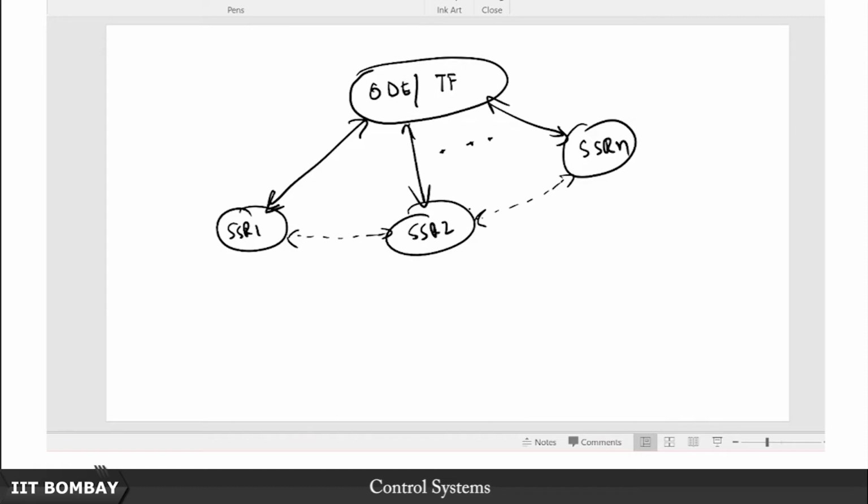These things are fairly routine in an advanced level controls course such as multivariable controls or any advanced graduate level controls course, but in this course we will probably not have the scope or the opportunity to address that question. Nonetheless, I can partially address some of this question and at least convince you that there does exist an infinite number of state space realizations from the ODE to the transfer function, and that is very liberating, because remember initially we started with this premise that the output of every integrator has to be chosen as a state.